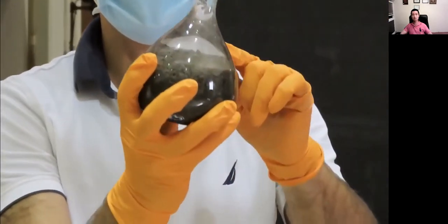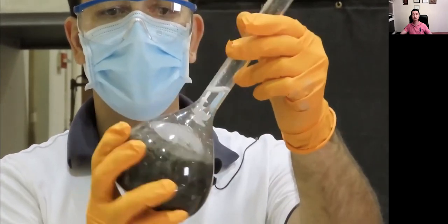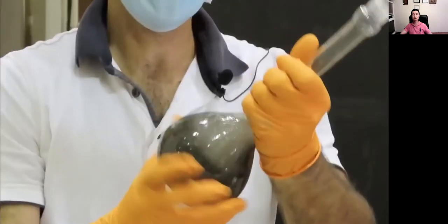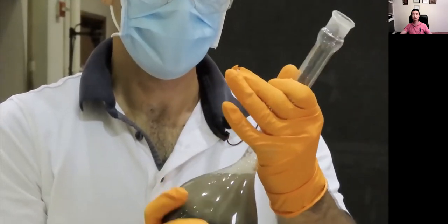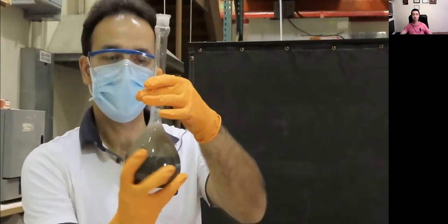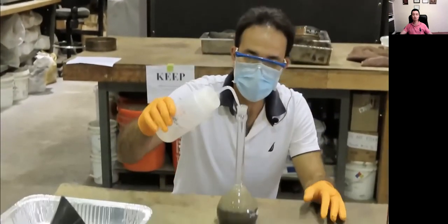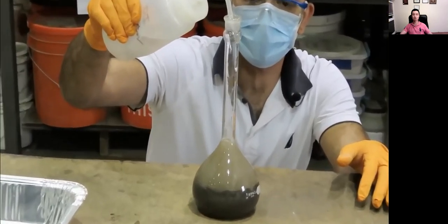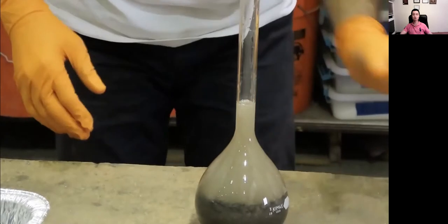tapping your sample. As you can see, as I move the sample, many bubbles come up to the surface. You can see it here better. So I need to agitate it, tilt it, invert it, whatever I can do for it. And the water level goes down even after a little bit of agitation. So I need to add more water because the volume was occupied by air bubbles, not real water. It goes down, and then I can redo it.